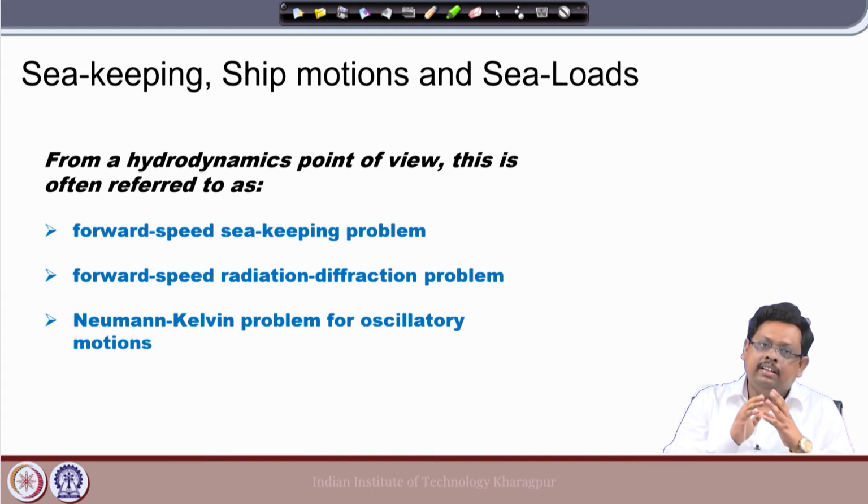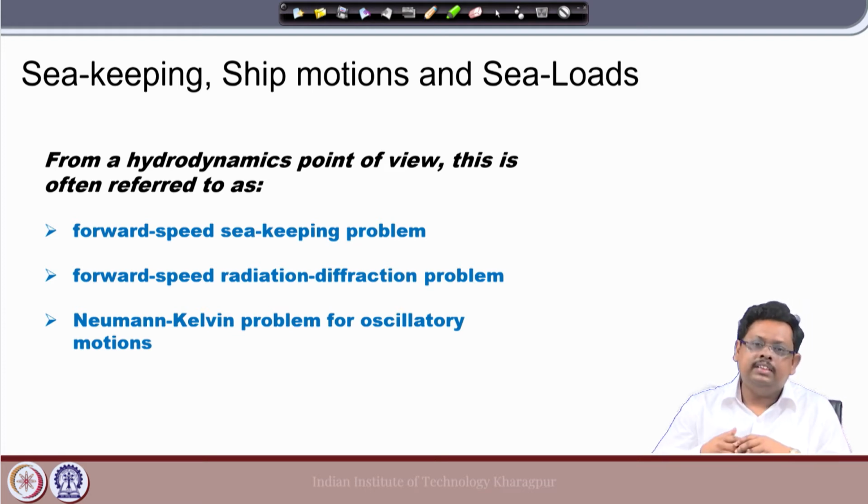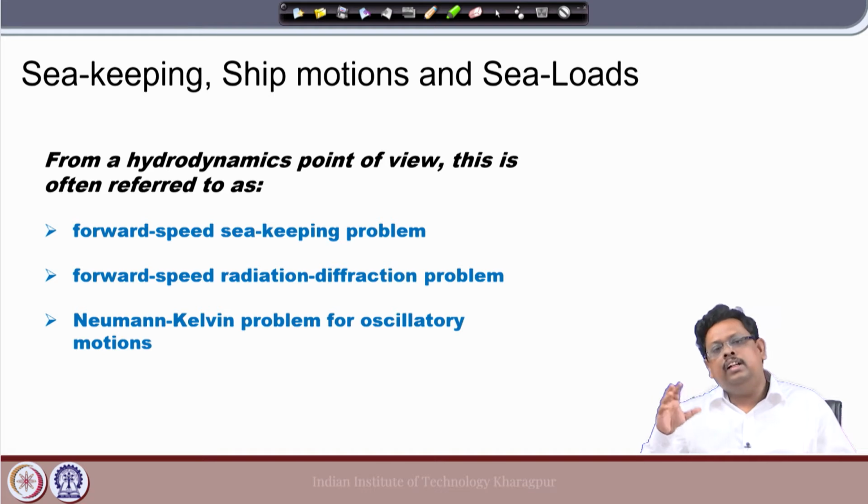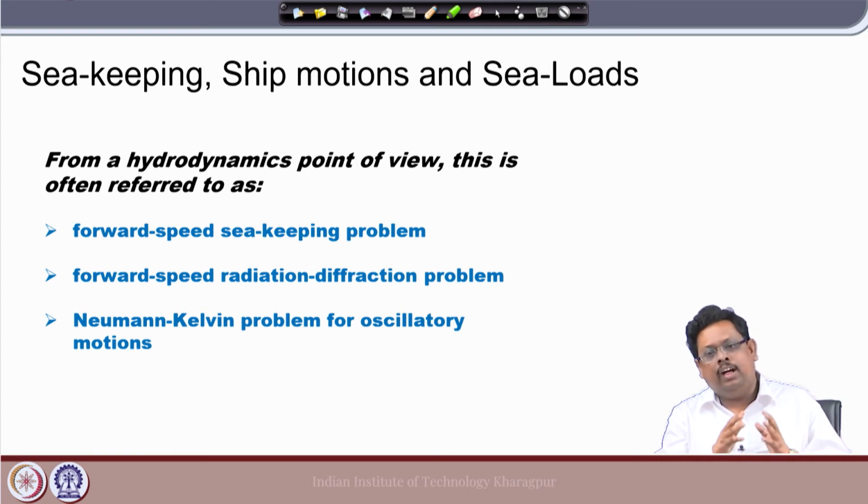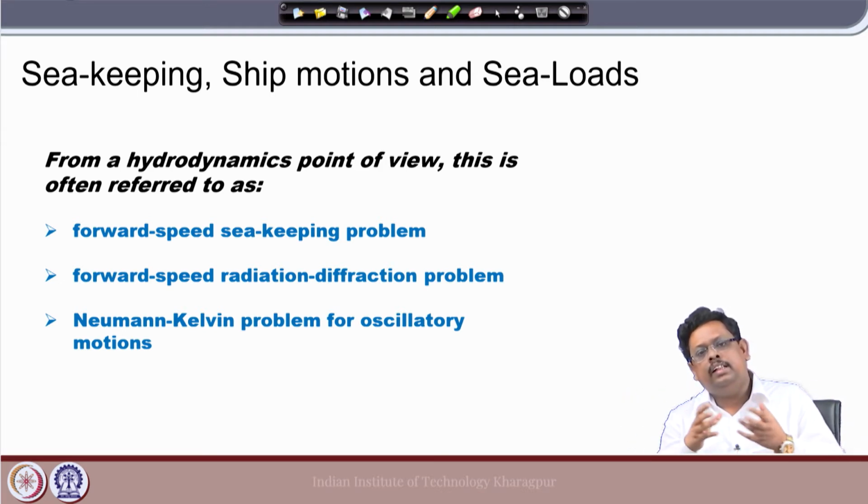Of course, we have another force which is very important. We call it the Froude-Krylov force, but we don't discuss the Froude-Krylov force much because we can analytically find the expression for it. However, we need a proper boundary integral equation method or some other type of solution to get the radiation diffraction force.